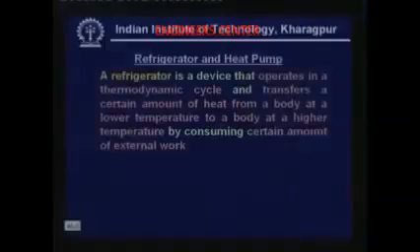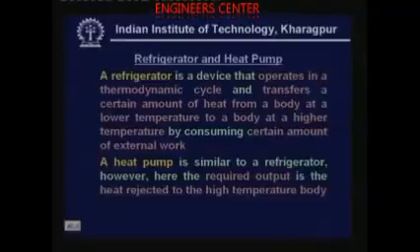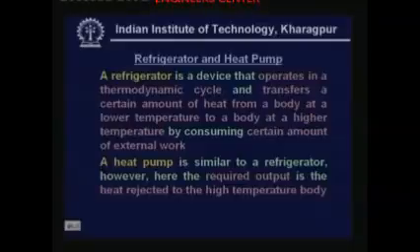Now a heat pump is, hardware wise, exactly like a refrigerator, but the difference is that in a refrigerator we need a cooling effect, whereas in a heat pump we want a heating effect. That means in a heat pump we are not interested in the heat extracted at the heat sink, but we are more interested in the heat rejected at the high temperature level. So from a practical application point of view, a refrigerant system can be used for summer air conditioning, whereas a heat pump system can be used for winter air conditioning.